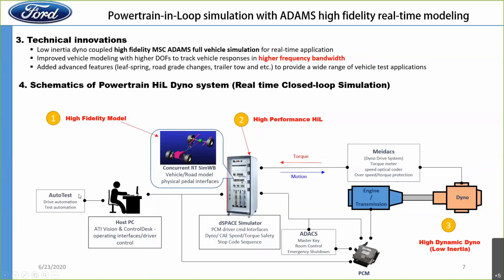Here we also set up the auto test with scripts, and we have the host PC to run the scripts. Therefore, there are three key components: one is the high fidelity model, two is the high performance HIL, and three is the high dynamic dyno. These three H's are critical for this system.